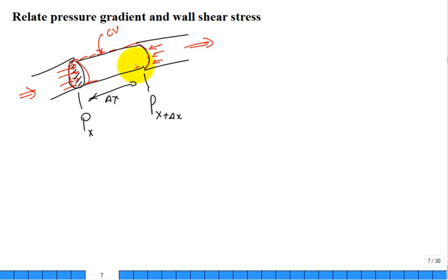So what I'd like to do is say, for this control volume, I have a fluid shear stress at the wall. What does the wall do? What type of shear stress does the wall induce on the fluid control volume? It's in this direction. How would I draw it? Like this. And I put the tau at the wall. It's a force per unit area, just like a pressure, but it's a viscous shear stress. And it's what the non-moving wall applies to the fluid in the control volume.